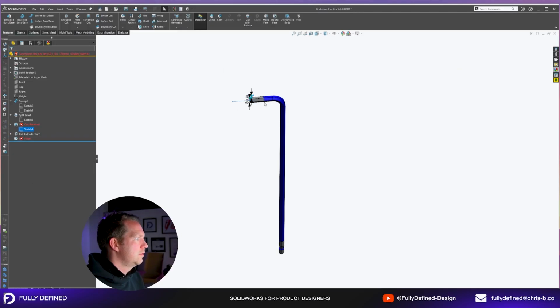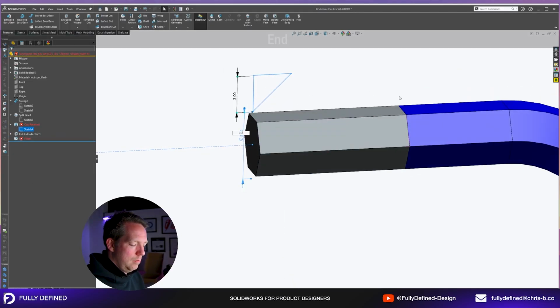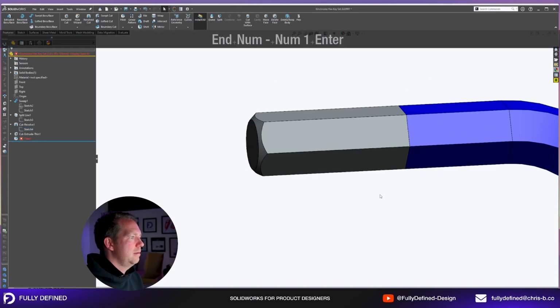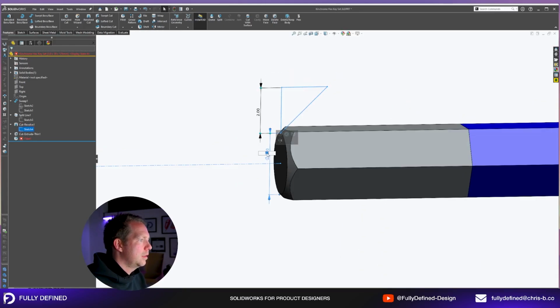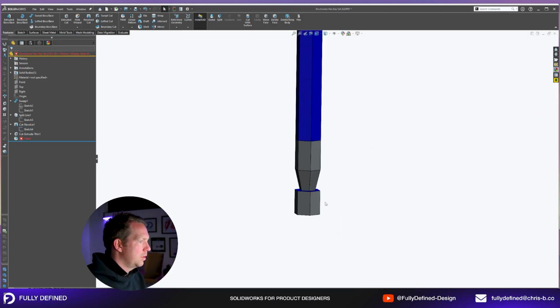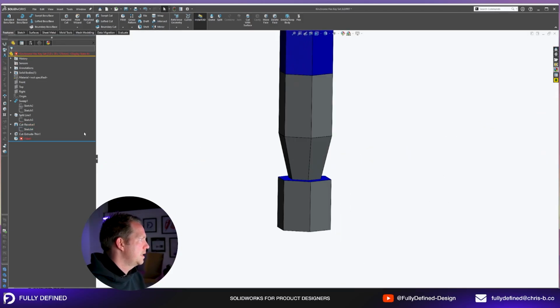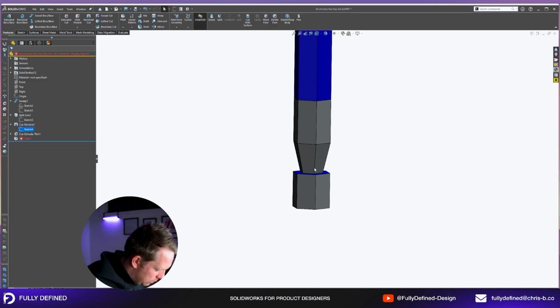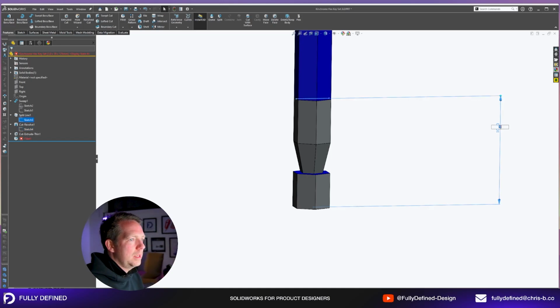My cut revolve, similar thing. -1, bring it in. That's a bit big. It can be 2.8. Oh, didn't like that. Okay, 2.75. At the bottom, now my fillet is getting too big in my cut revolve, and my split here needs to probably change as well. So a split is down to 9mm.